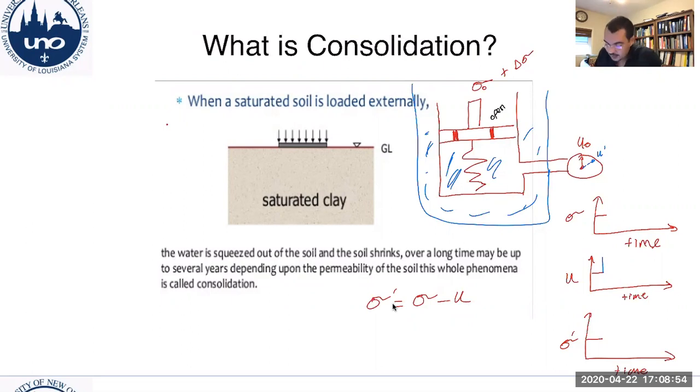What's going to happen is the extra pore water pressure, after we open the valve, is going to start to go down, and it's going to keep going down until it levels off to whatever initial pore water pressure we had. Now, the effective stress is going to increase because the pore water pressures went down.